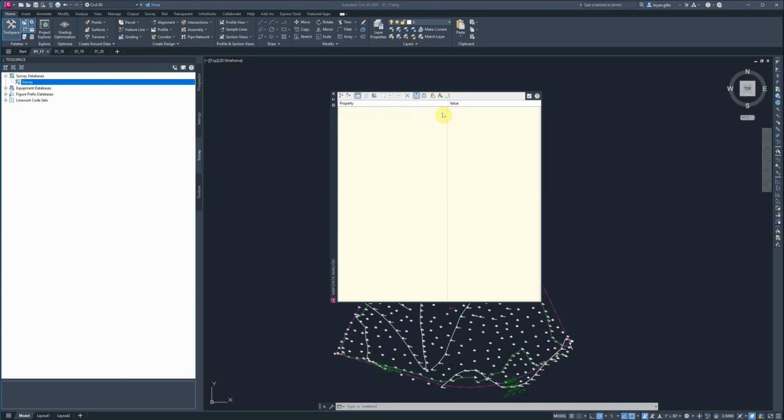If you're running a version prior to 2025, you might just have a document sheet with an asterisk and a check mark. In Civil3D 2025, it'll be the globe one. So go ahead and click that. Then you're going to have a prompt to add a name. Go ahead and type boundary.